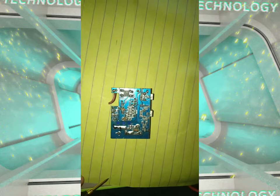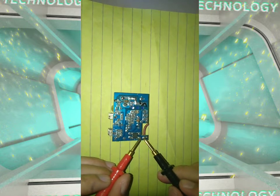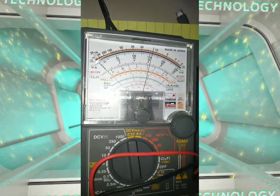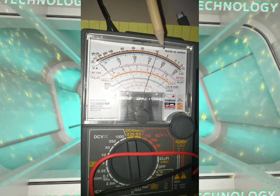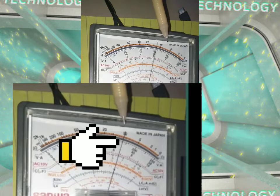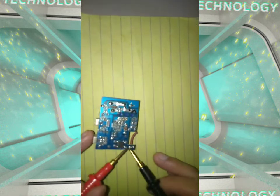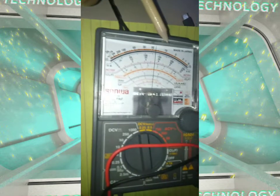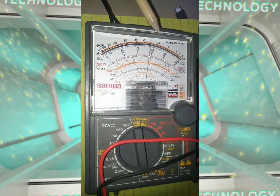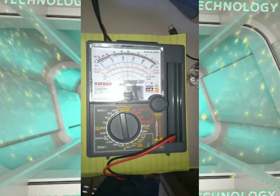Now, I am going to look for a resistor that has a function. Let's have this one and see if it has a function. As you can see, the needle pointer points at number 10. So 10 times 1 is equal to 10. The reading here is 10 ohms. I get the 10 ohms from the reading of the resistor that we measured, times the setting, which is 1.